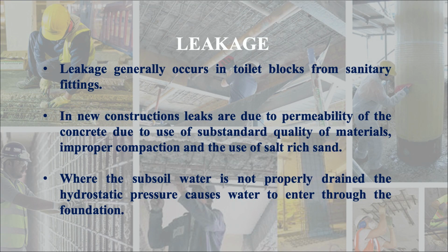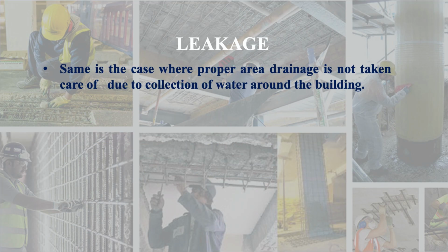Where the subsoil water is not properly drained, the hydrostatic pressure causes water to enter through the foundation. The same is the case where proper area drainage is not taken care of due to collection of water around the building. If due to poor drainage system or poor drainage arrangements, the water will be collected around the building and there these problems will be there.